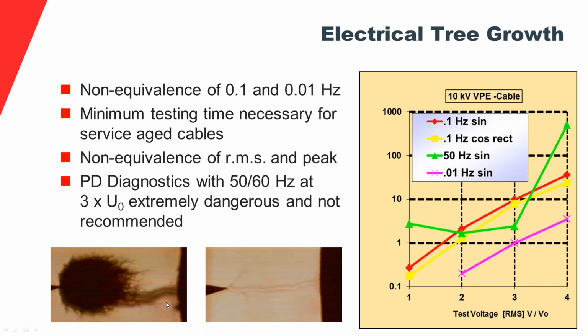On the left, you have this tumbleweed structure, and this is what explains also the acceleration of the VLF of the electrical trees, because the gas pressure is not forming this very distributed, concentrated bush type of structure. It's a very straightforward progressing failure mode when you use VLF, and this is why the test is effective.